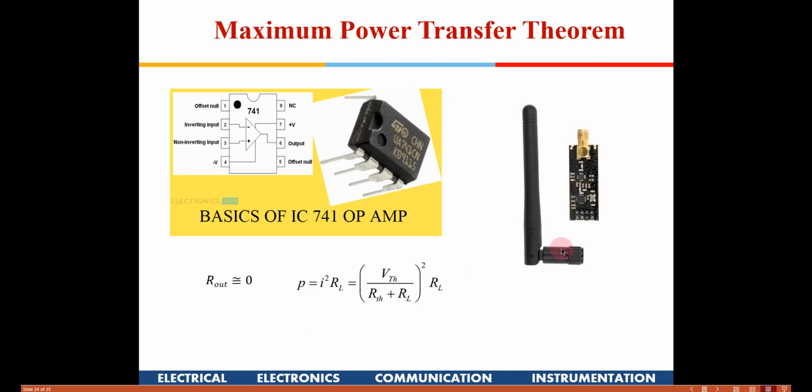This is an antenna. Okay. Most of the RF antennas are of 50 ohms impedance. I'm just giving you some practical applications of this. So whenever we design an LNA, that is low noise amplifier, that is the first amplifier which couples the antenna to our receiving station. It could be mobile. Mobile also will have a small patch antenna.